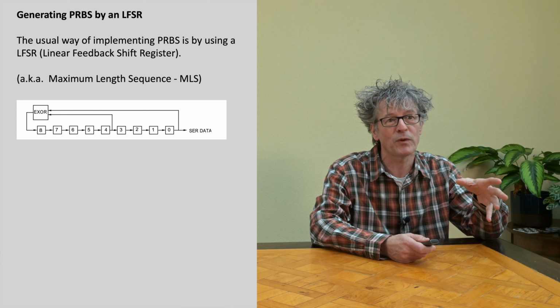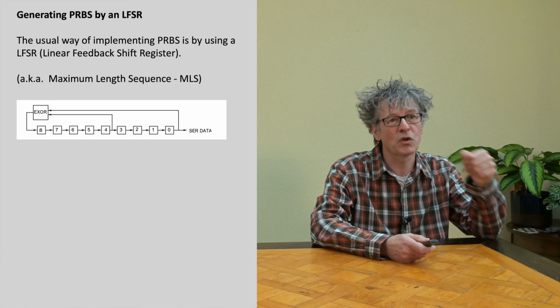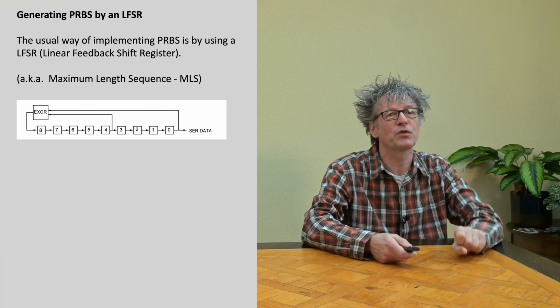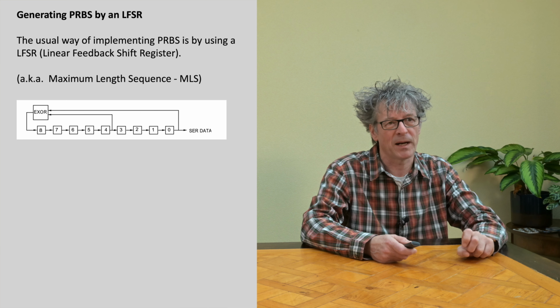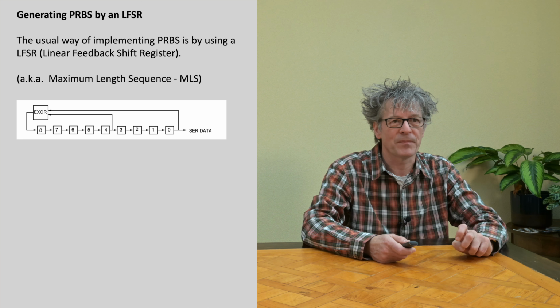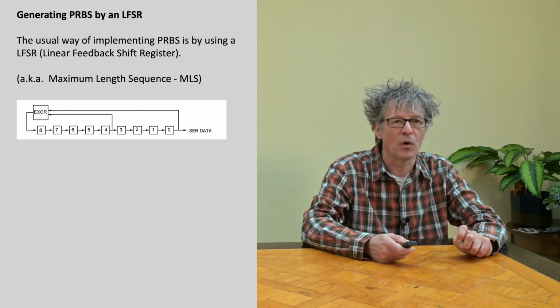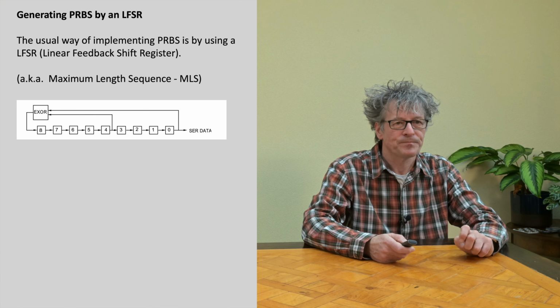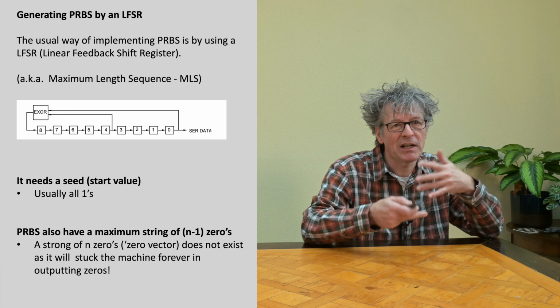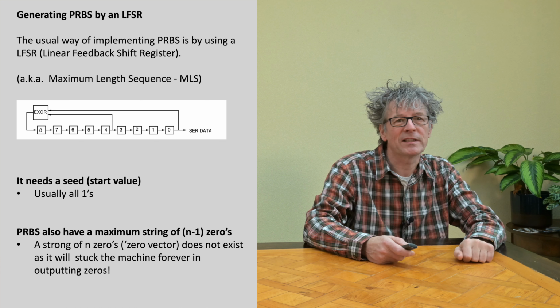We've got a number of shift registers. With every clock signal, everything shifts to the right, and the first register is being fed by some kind of algorithm. And here you see this particular code length of 9. This algorithm is an XOR of position 4 and position 0. Now, you need a seed. When you get it started, you need to feed the register with starting values.